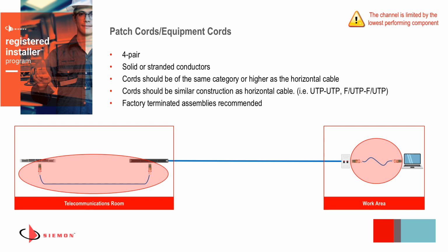These can be solid or stranded, but are typically going to be stranded conductors. Stranded conductors tend to be more flexible. And so when your patch cords are the part of the installation that are constantly moving and being routed, you want to introduce that flexibility. You'd see solid situations perhaps in a cross connect scenario if you want to address that cabling in from the switch to the first patch panel. Solid cables are a little bit easier to manage and form and bundle together.